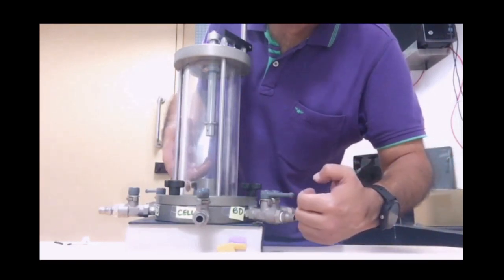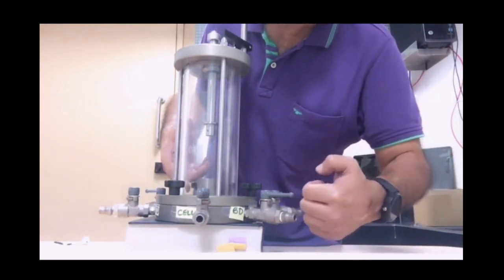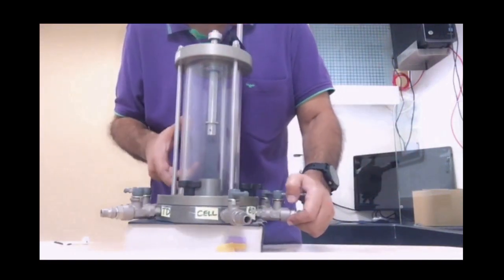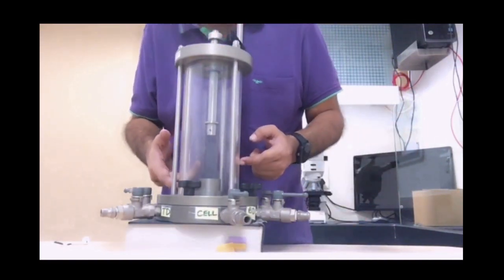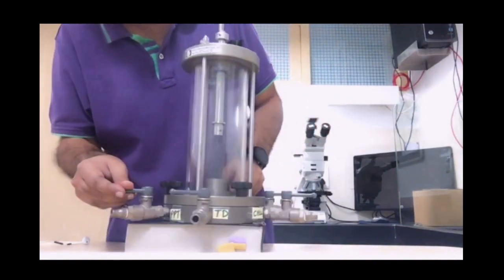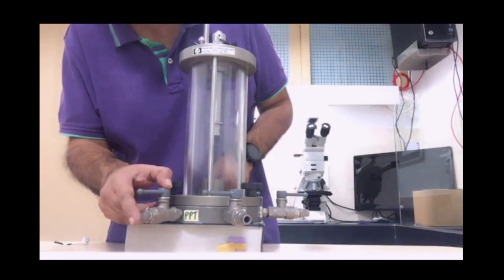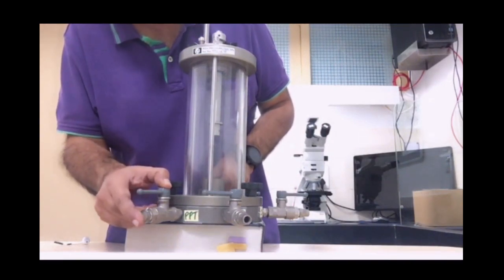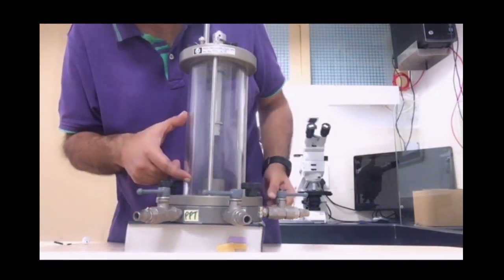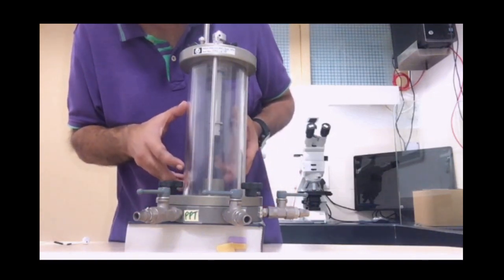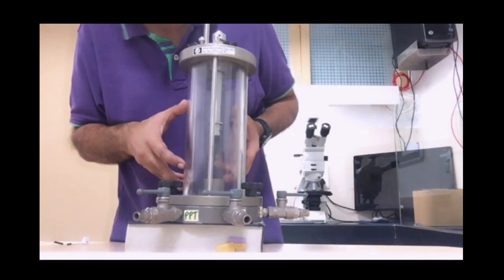So once it reaches a value of 190, it's going to stabilize with this, and this 190 would be within the sample. Remember, 190 goes from the bottom, and within the sample I can read 190 from this pore pressure reading. So once this PPT reading gives me 190, I can be assured that whatever back pressure I've applied from outside, the same is within the sample throughout. You have the same value.